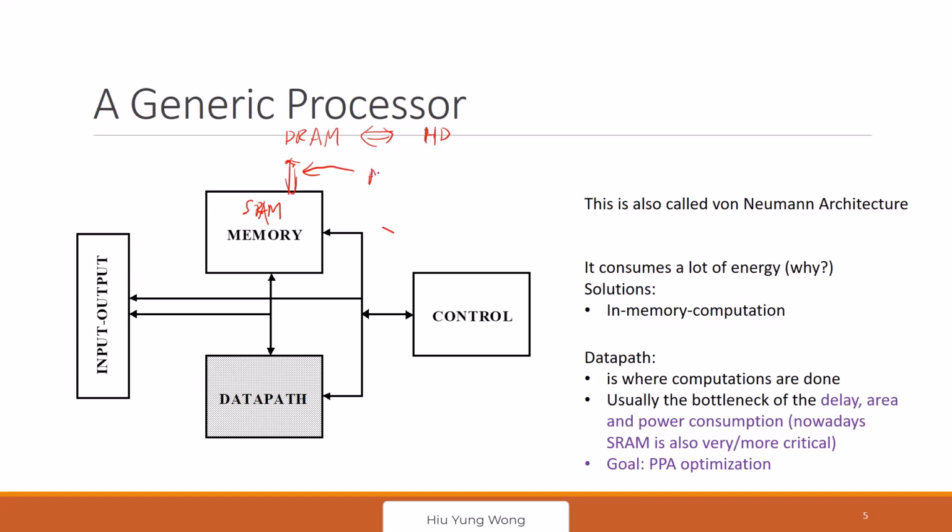Sorry, I should say MRAM, magnetic RAM, which is already in very good shape in production. They are non-volatile, and at the same time, they are very fast. Not as fast as SRAM, but they can be smaller than SRAM, and also consume less electricity and are non-volatile compared to SRAM. And between DRAM and hard drive, of course, now we already have this flash memory, right?